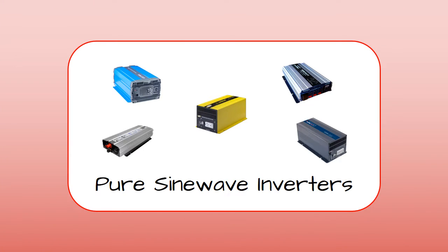These are examples of pure sine wave inverters. These units will provide the sine wave output that we saw in a previous slide. You will see these in off-grid environments, as they cannot have their output connected to the grid. We reviewed solar inverters in a previous video. Solar inverters actually sync their output to be in phase with the grid frequency, but these inverters just output the frequency on their own, which will be out of phase with the grid and therefore will be damaged.